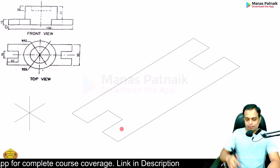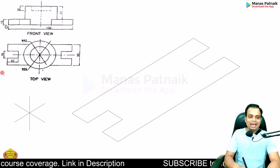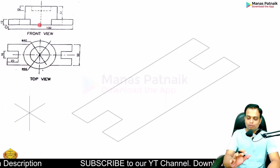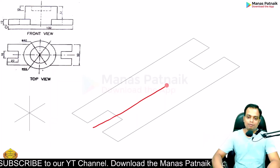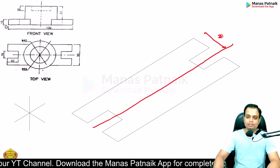Now what we can do is begin by creating the entire top view first, and then gradually we'll be providing the heights, as given in the front view. Don't worry about that. The center can be located very simply. This is 50, so half the center would be somewhere along this line. This line is at a distance of 25, isn't it?